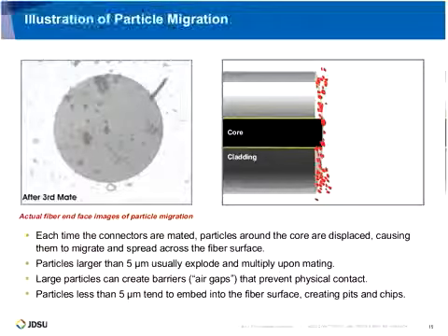But the point of this was really to show that even if you don't have the debris on the core of the fiber, when you mate that, you still run the risk of potentially damaging the performance of your network, because it could send that debris all throughout that fiber interface, including the core. So therefore, you do need to be mindful of the debris, not just on the core, but in other places of the fiber interface as well.